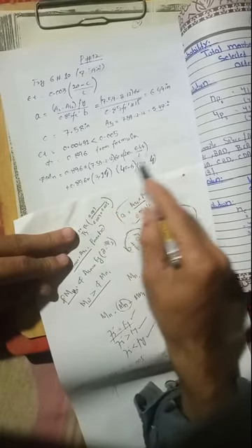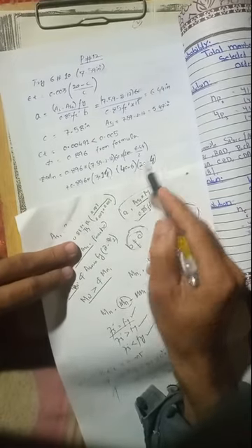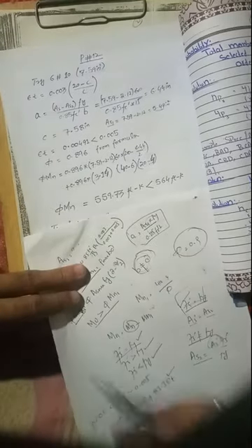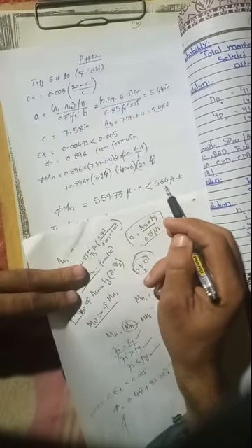Now you just calculate the moment capacity, and the moment capacity, we already know this equation. This is for tension reinforcement and this is for compression reinforcement, right? So we see that the moment capacity 559.73, which is less than 564.